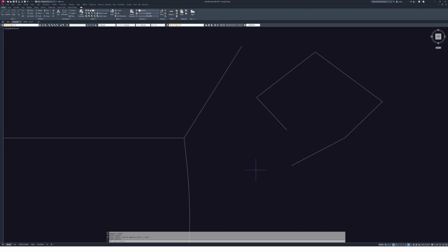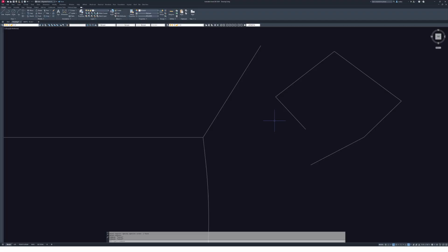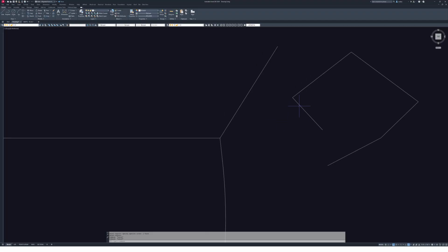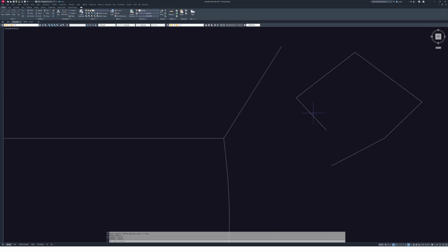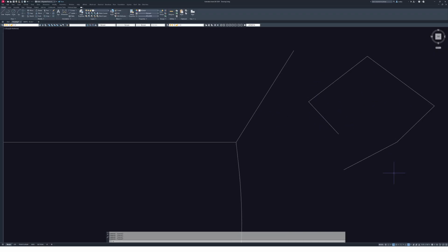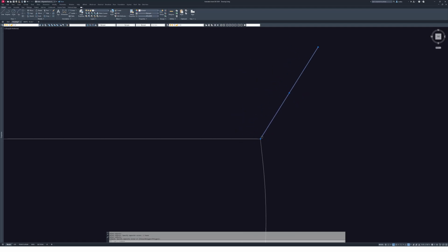So whatever the bottom left of anything is, relative to its own absolute lines, is where the insertion point will go. So if I just draw a simple line like this, the bottom left will always give me an insertion point right there. So I'm going to do Control X, Control Shift V creates a block. And so I can just drop it right there. So now this is a block.